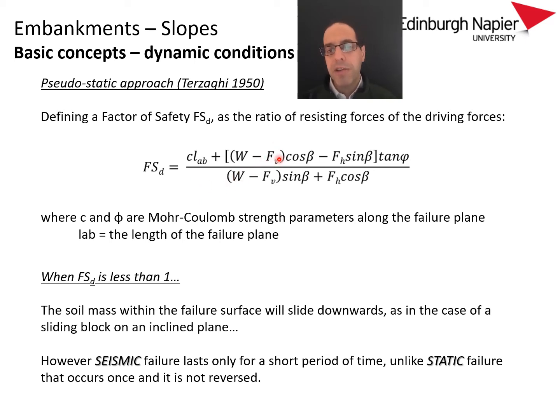It's just that now you have those Fv forces and Fh forces factored in as part of that pseudostatic approach of analysis. Of course, you would expect that factor of safety to be bigger than 1, because if it's less than 1, the soil mass within the failure surface will slide.